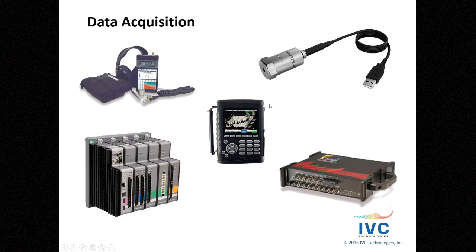The analyzer shown here in the center is one that we've used frequently, specifically for crane testing, where we have to have a larger channel count. We can record up to 16 channels of vibration, and it's also battery powered and very portable, so we don't have to drag AC power supplies and extension cords to accomplish a multi-channel test.